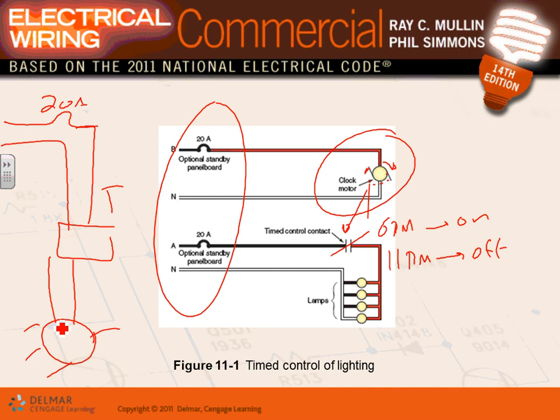Does that make sense? What I want to emphasize, you guys are doing the site today for chat, right? When you go to Revit, Adam, this is exactly what you're going to do. You're going to lay out your fixture. You're going to put timer 1 in the mechanical room, and you're going to circuit this fixture from circuit number, I don't know, say, 24. So now it's circuited. This is fixture W, and it's going to be switched. The circuit is 24, and the timer that's going to switch it is timer 1.